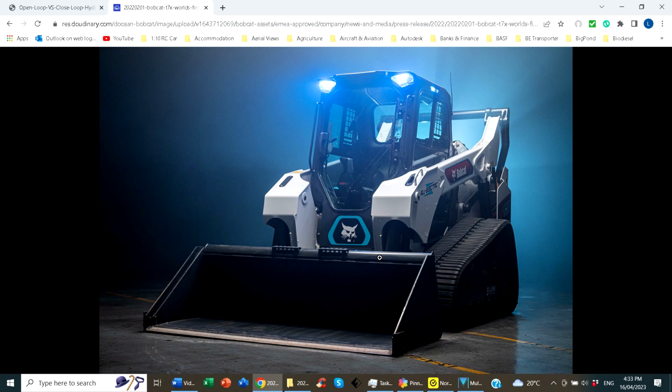Now, I'm a mechanical engineer. I trust hydraulics long before I trust electrics. But in the right application, electrics is a lot simpler and you can do a lot more things with it. You just can't fix it yourself. Pneumatics are a lot easier to troubleshoot. Now, the hydraulic or pneumatic decision might be somewhat taken away from you if the engine is air start. If that's the case, you've already got compressor and tanks and valves and so forth on board. So the logical thing to do would be to try and do the other functions with pneumatics.